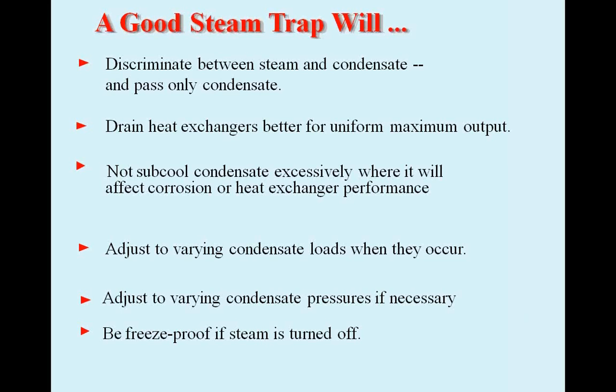You have to have water at the trap, and the trap will open or modulate and let that out. But you'll always have some condensate backed up, and you want to minimize that. If you back it up too far, again, using the soup as an example, you'll back it up into the jacket, and you won't get the thermal transfer that you're looking for.